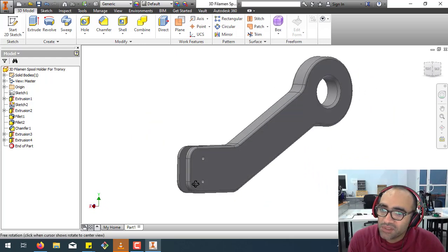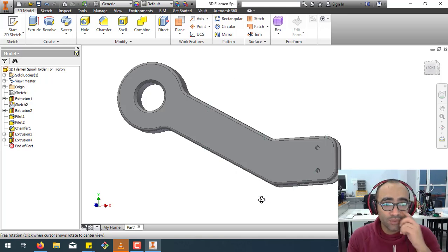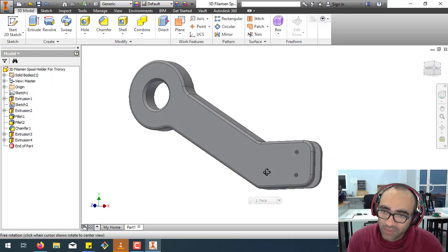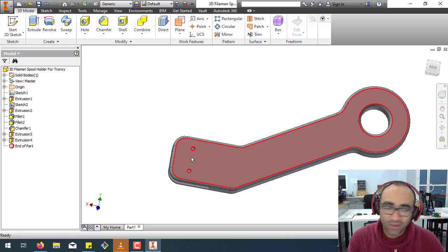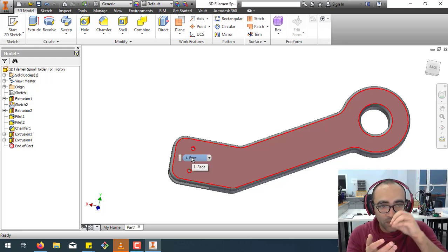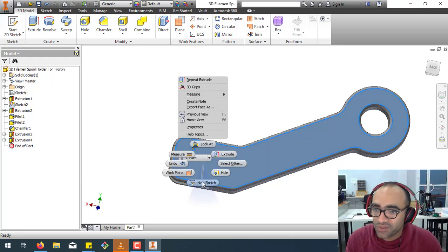What I'm going to do is use 3 mm screws, and we are going to use the 5.6 mm nuts. So in order to keep the nuts in their place, we either make a wall for the nut to go in, or we can engrave in the same body of the 3D printed part. So let's engrave it inside.